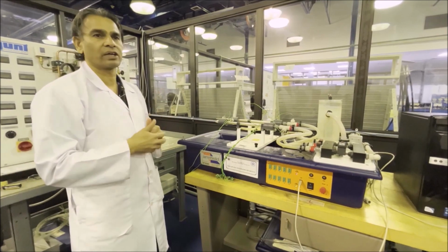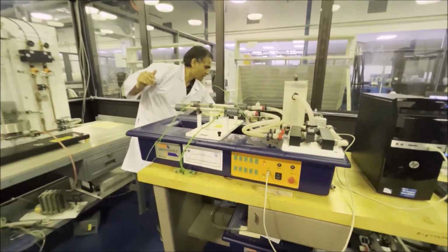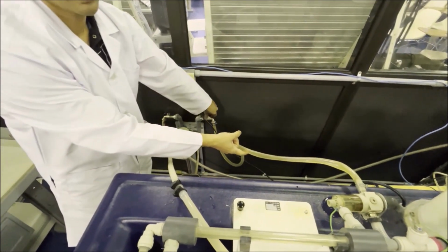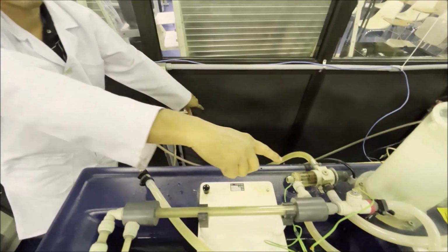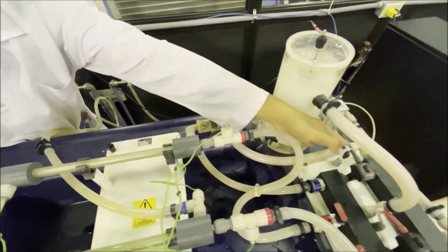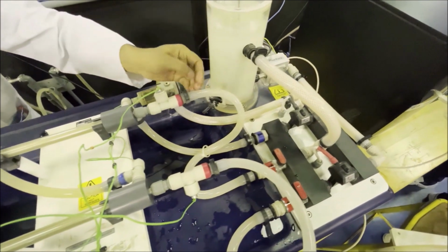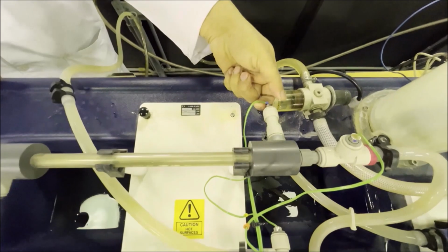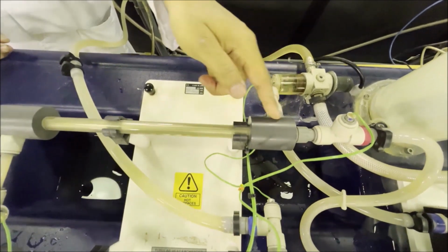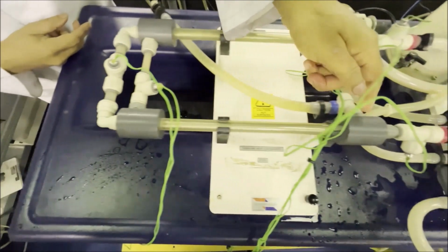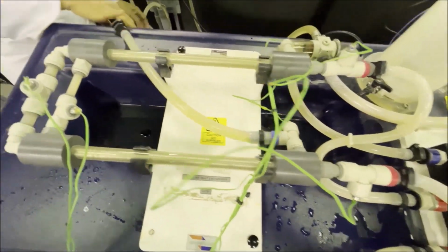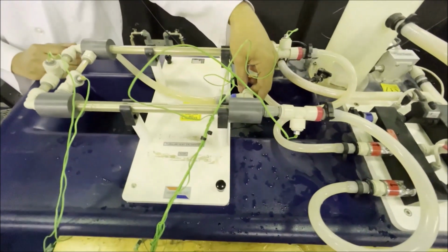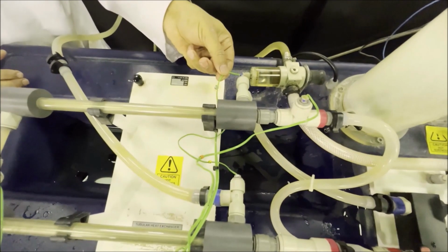I will explain to you the water flow. So this is cold water. Cold water is coming from here, so we need to switch it on. If you switch it on, the cold water will flow from here, come here, and this thermocouple will give me the cold water temperature. The cold water is flowing like this and coming out, and through this point we can drain the cold water. So this is the outlet temperature of cold water, this is the inlet temperature of cold water.